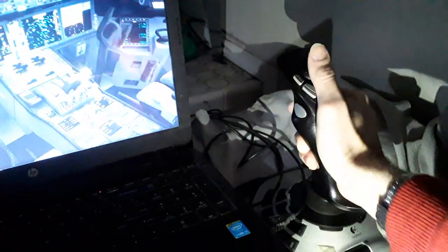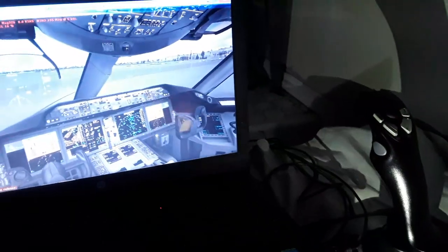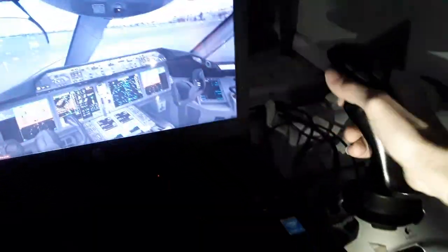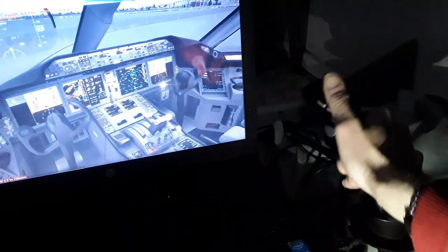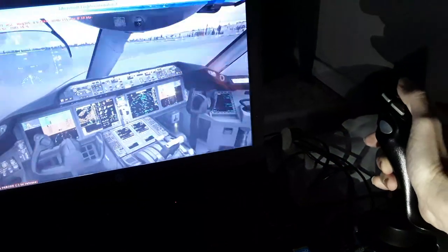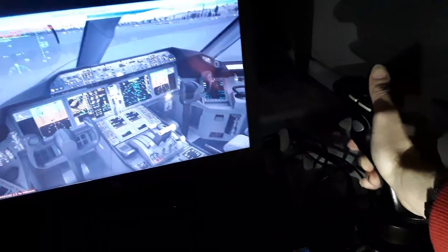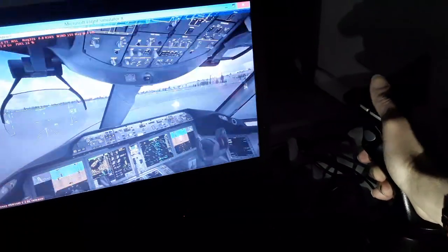So I was talking also about the flight controls, how you can control the aircraft over here. You can see I'm using the side stick to control the horizontal tail for climb and descent. Also make turns to the left, turns to the right. It's a fly-by-wire aircraft, so it has flight control computers on board. When you move the side stick, you give an electric signal.